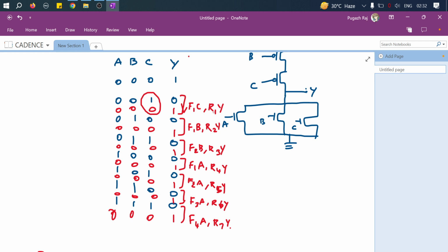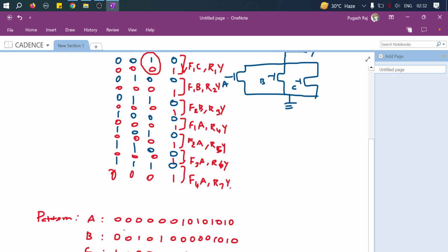Like that, you have 7 methods to calculate, and you have to feed the inputs like this. Where I inserted zeros, I am keeping them here. You have to give the inputs through stimuli to find the delays as well as power. So we have to give this exact input, so that you all get similar outputs.